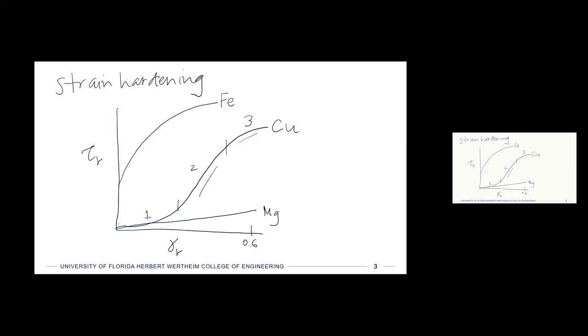So down here is where we talk about first yield, way down here, right? And then the resolved shear stress in PSI is going to be anchored at the top of this plot, something like 12,000. So I'm just going to write 12K. So we can get very significant strain hardening, especially in iron-heavy alloys like steel, right? So we sort of know that already, having studied some of these materials.